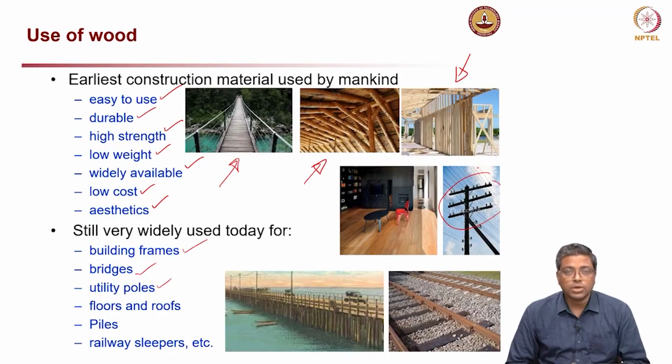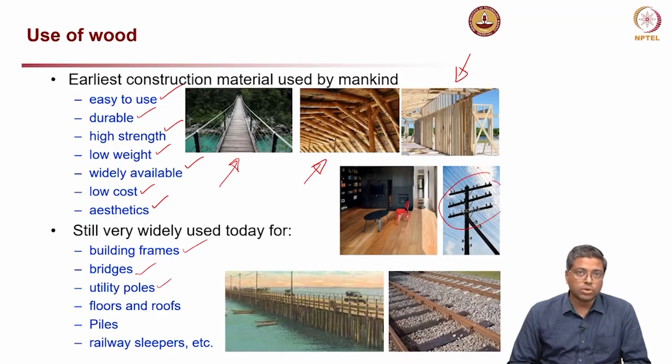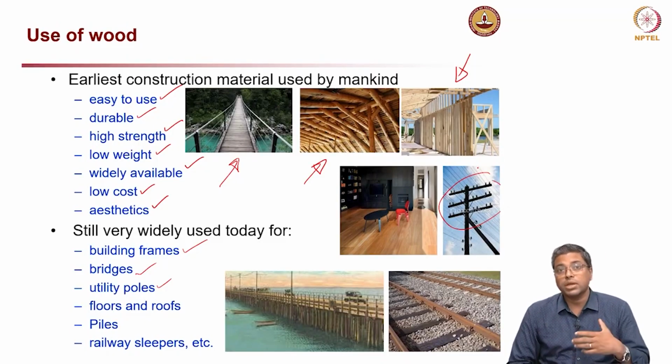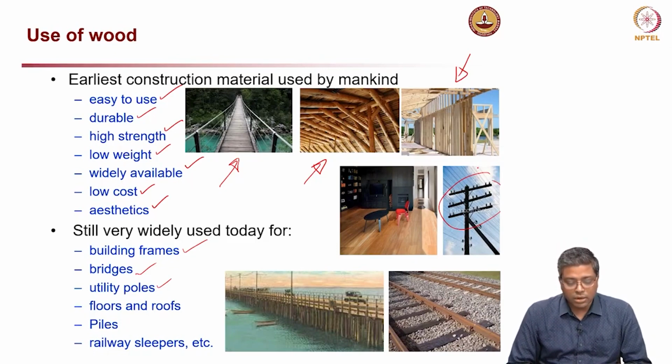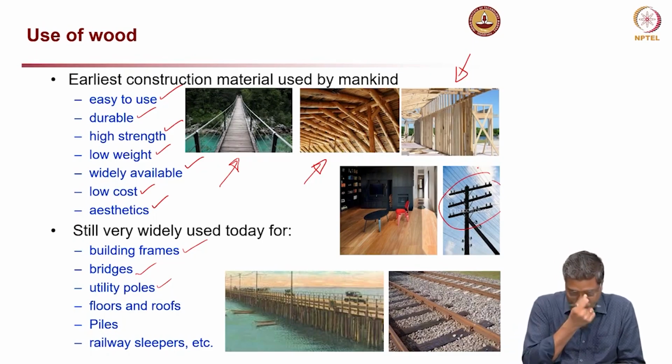We are starting to use reinforced concrete or pre-stressed concrete poles depending on the load carrying capacity required. Sometimes wood may not be sufficient to handle the load, and at the same time the availability of wood may not be that easy. So we go for reinforced concrete, and also we talk about a large number of such products. So concrete is also being used nowadays.